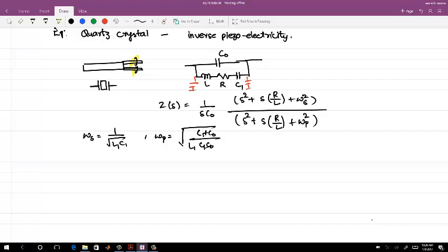So the thing is, this crystal oscillator frequency, no matter what they are made of, is generally very limited, and that is because of what dimensions you can carve out and how stable they are. So this is generally lesser than 100 megahertz.